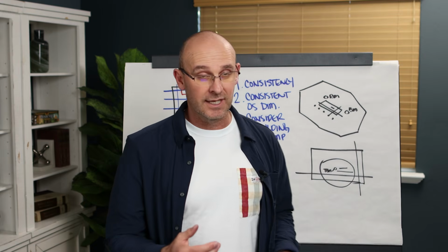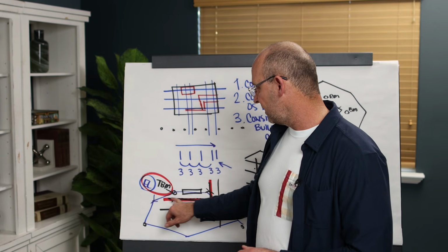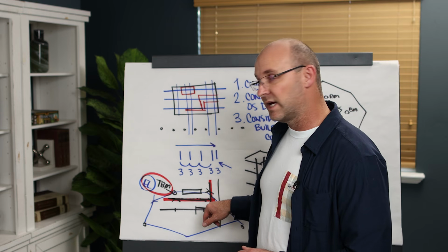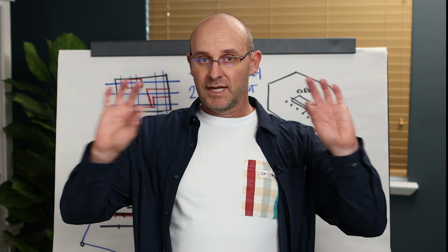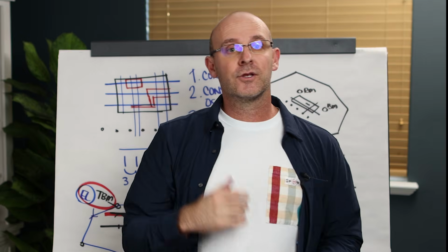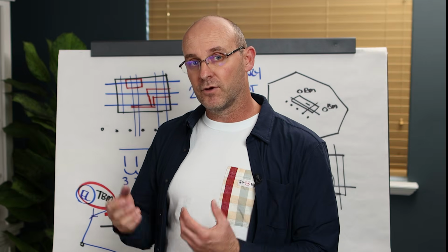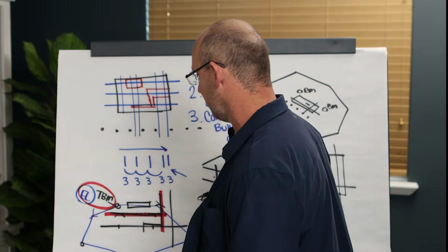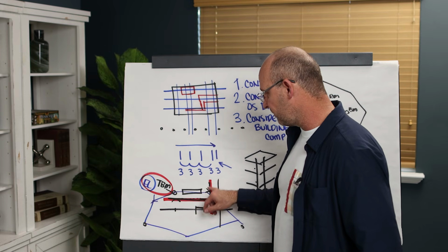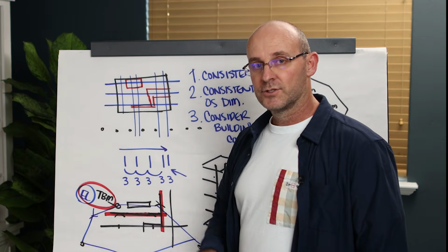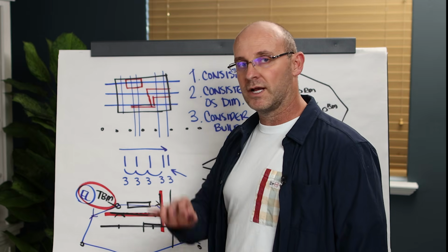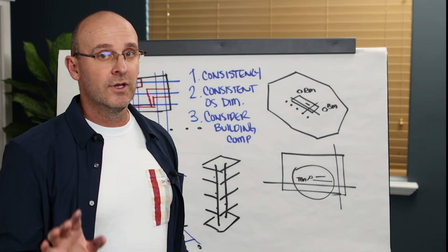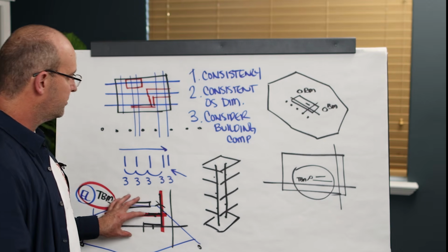So one of the things I like to do is, if I'm doing these lines, I might spray down clear coat on the slab before I snap the line, let it dry, then snap the line, then clear it again, so that one of these days when we're polishing that floor, those marks will just come up and I won't stain it if it's exposed concrete. But the bottom line is, these should be temporary marks specific to the component. So it could be for embeds, it could be for wall height, it could be a 4-foot offset line on the form, but working control needs to be a communication between you and the craft.